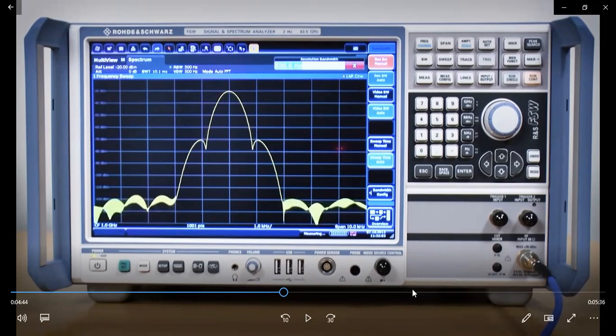So if there is a significant difference in the power level between 2-3 kilohertz components, you can find that out when you set the RBW to 3 kilohertz. But with 30 kilohertz, they all will just merge. You cannot separate between 2-3 kilohertz components, or your granularity is now poorer. The resolution that you work with is now poorer.